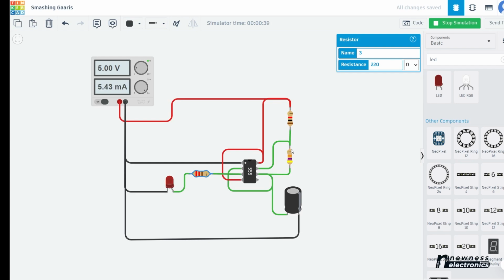Now I'm going to have you do this because part of the final project is to build a simple inverter. And we're going to be using this astable in the final project to build this simple inverter. So this is your assignment. The assignment is to create an astable multivibrator that oscillates at 50 hertz. So your frequency is 50 hertz. That means you have to find the value of this resistor and this capacitor that will give you 50 hertz. All right, have you learned that? Okay, let's continue